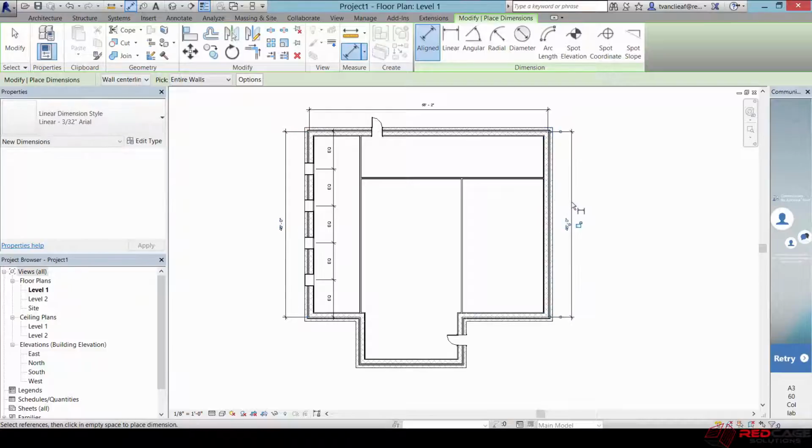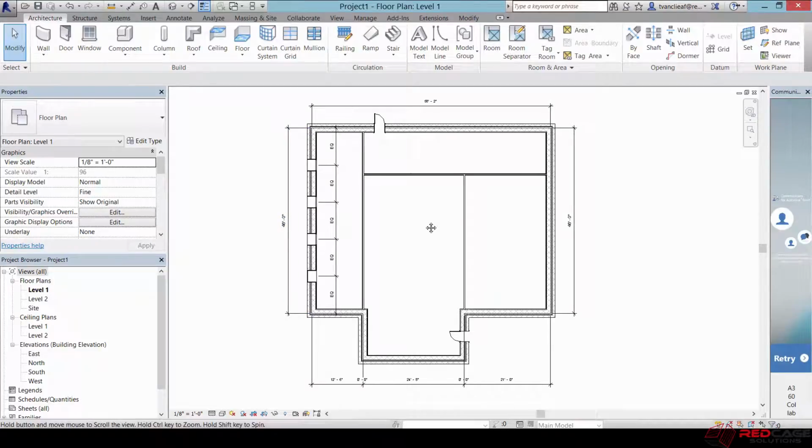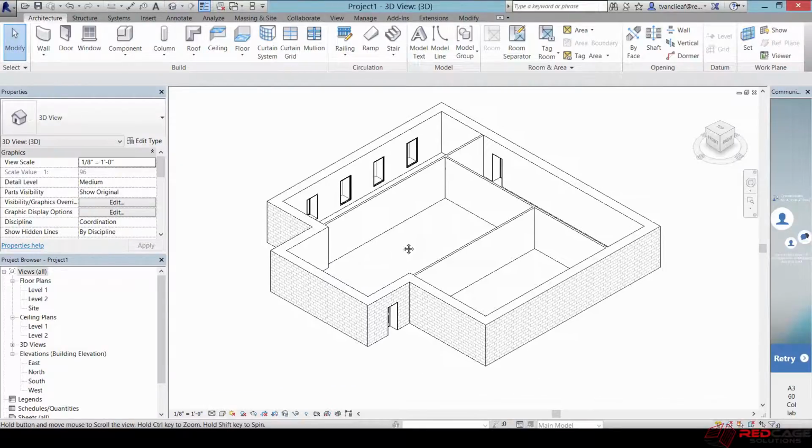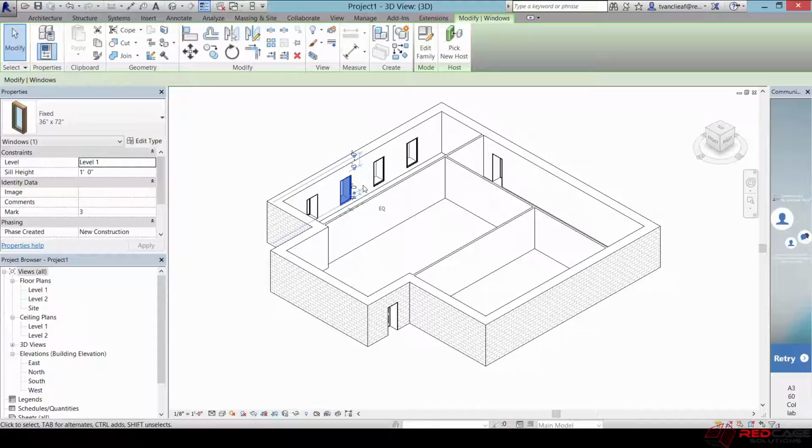But you can also check your work quite easily by just toggling that 3D view. So after you've spent a couple of minutes developing a concept or an outline, you can come up to this house icon and check your work. So anything that you do here in 3D or in 2D is going to modify in each level. So this is what we call bidirectional associativity.